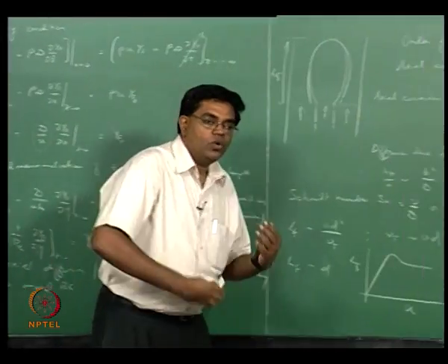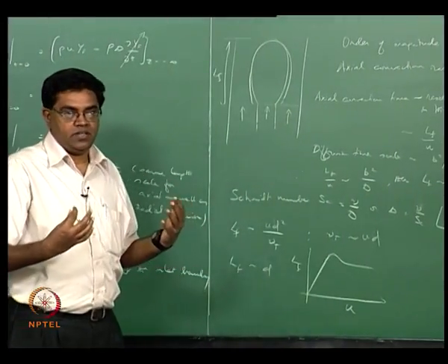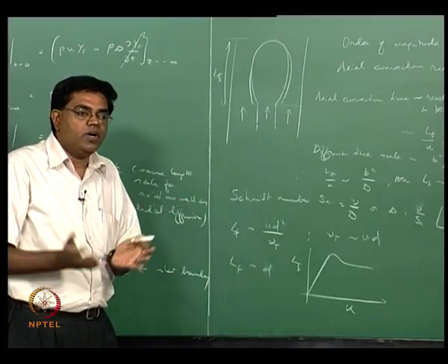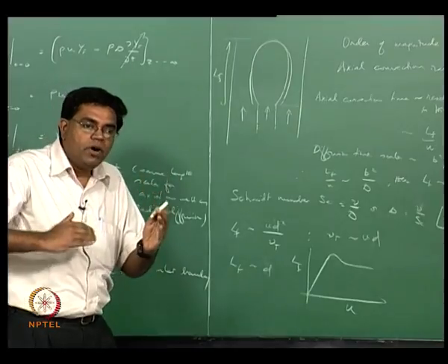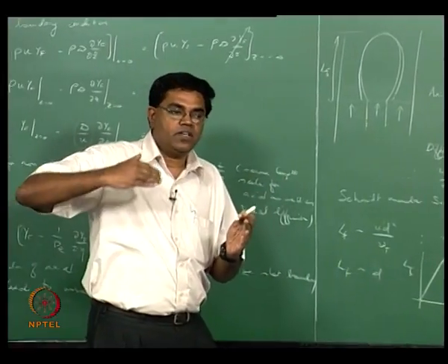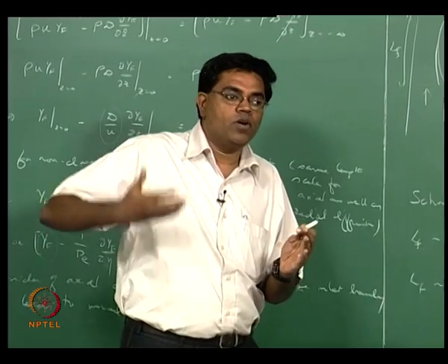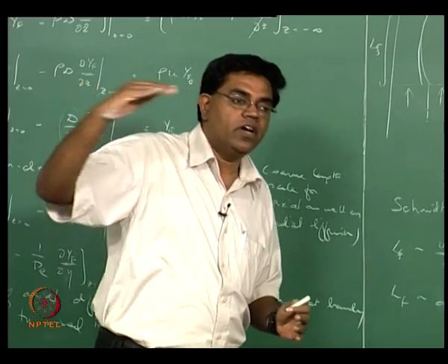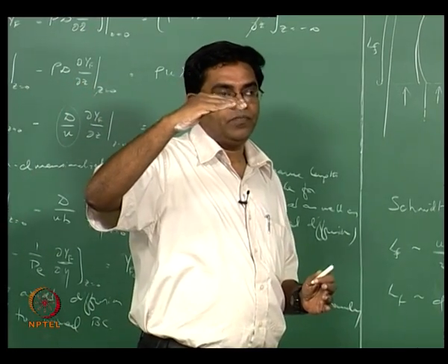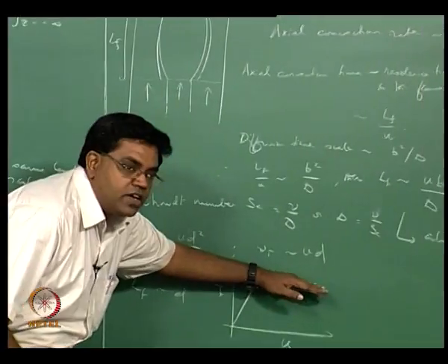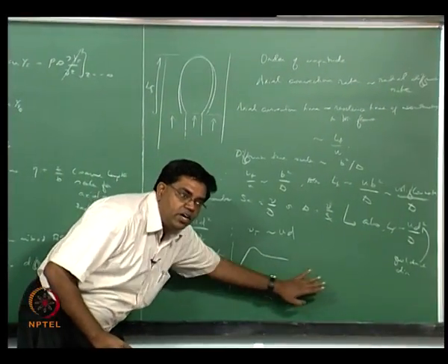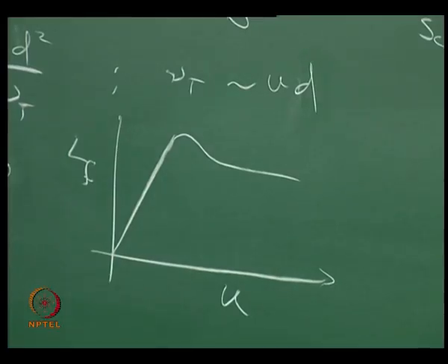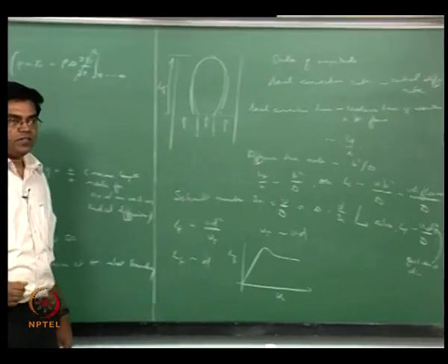Why is that? Because more and more mixing is happening, and as more mixing happens, the fuel and oxidizer burn in stoichiometric proportions much closer to the burner. That becomes insensitive to the flow, because more and more flow, more and more burning, can happen within a pretty much constant distance. So that's essentially what's going on as far as turbulent mixing and burning is concerned, and therefore you have a flame length that is pretty insensitive to the flow velocity.